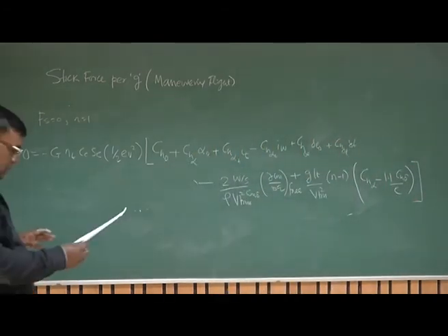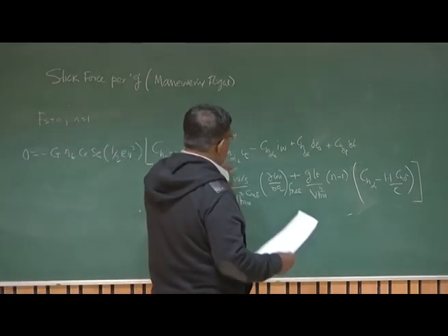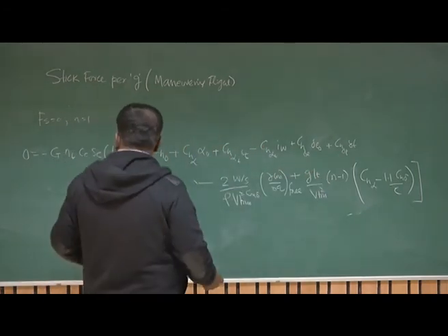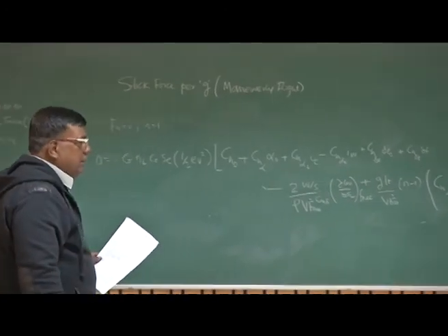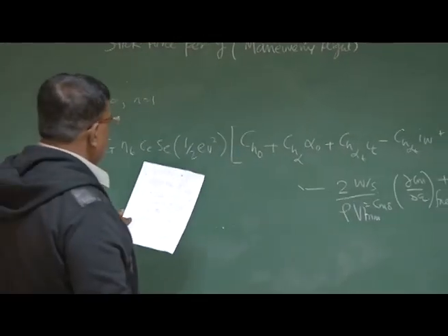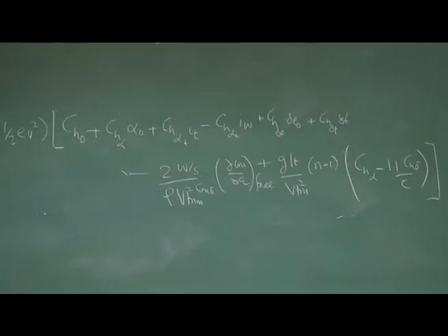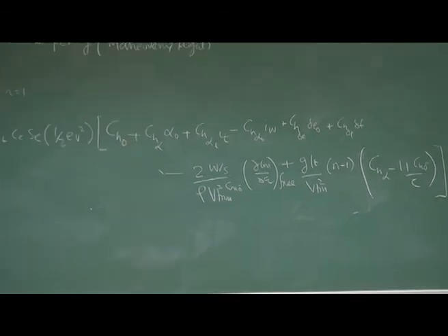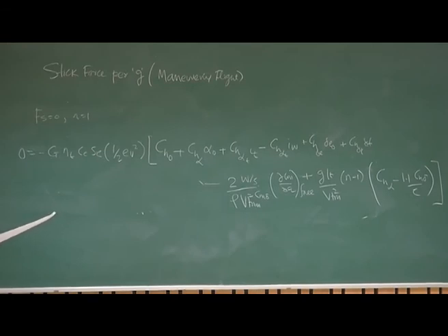Now see here. If I put n equal to 1, then you will see that this whole will correspond to the case where we had level unaccelerated flight. The same term will come here, right? That shows that we are in the right direction. That is the stick force for level unaccelerated flight. When I put n equal to 1, those terms go to 0, and exactly that Fs expression will develop for level unaccelerated flight, which is cruise flight.